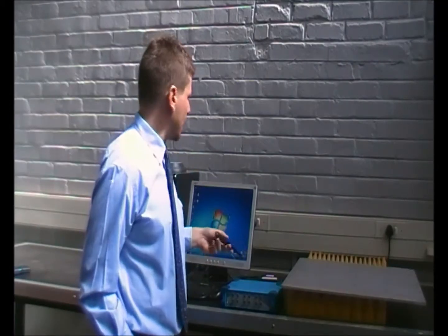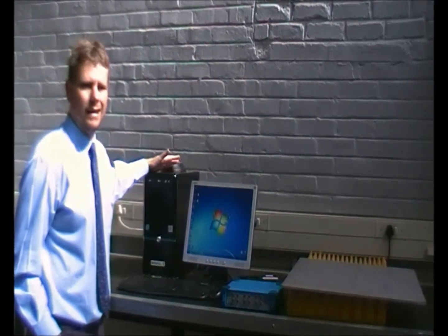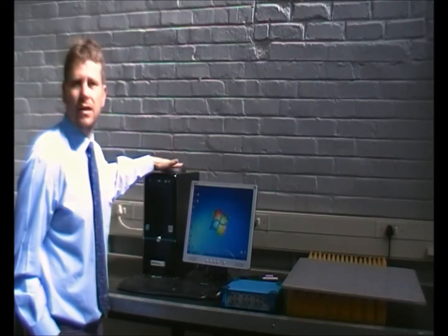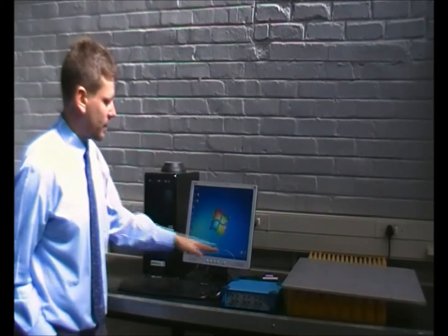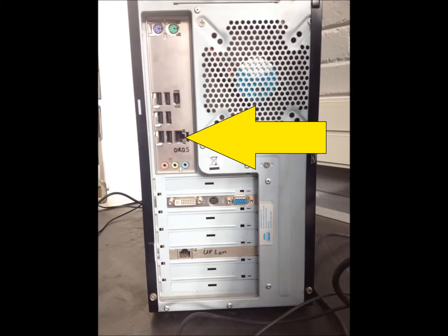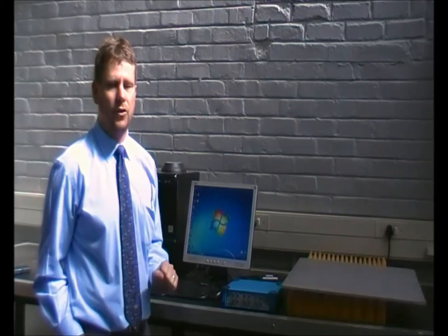Now, in terms of our actual hardware, on the PC side, we have the Modal 2 dedicated desktop PC, which we've aptly named the Modal 2 PC, with the necessary dongles installed for the licenses. And over here is our OROS OR35 analyzer. It connects to the PC via LAN, and there's a dedicated LAN port for the OROS that is clearly marked, so you can just connect it there. You need to use the correct IP settings, but that has already been set up on the desktop, and there is a document on the desktop for your reference.